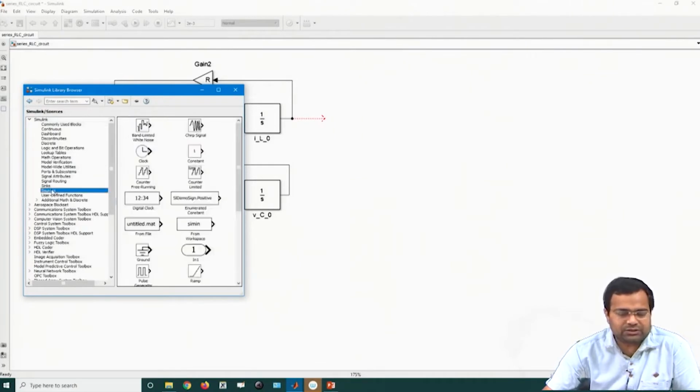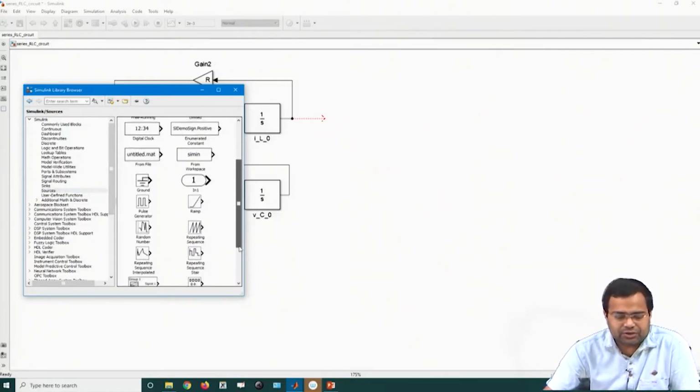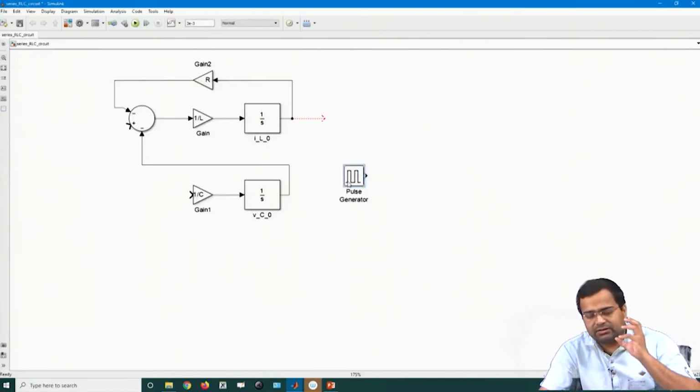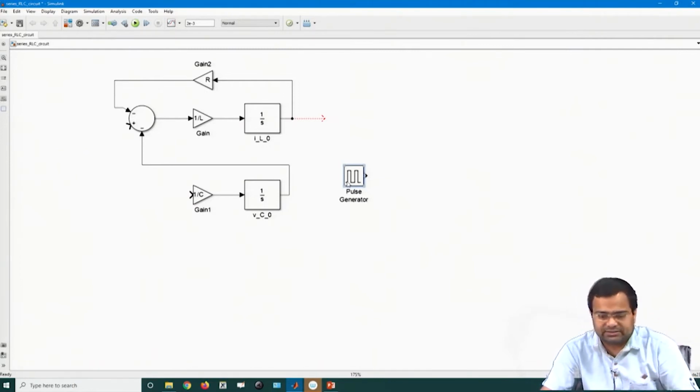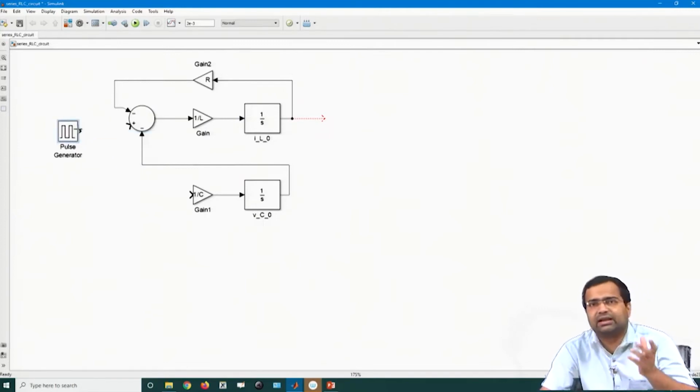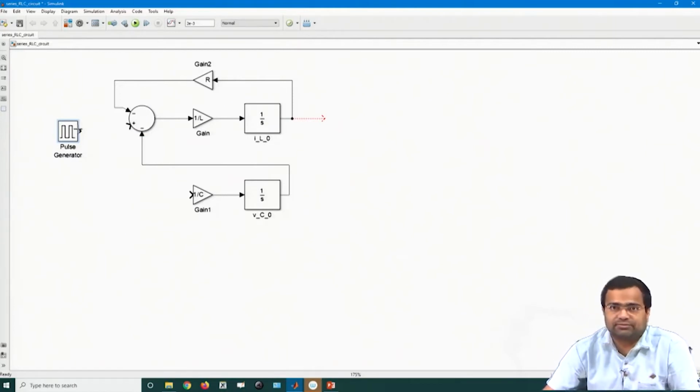If you go to source, in the Simulink library, there are various types of source. So, let us say I choose a pulse generator, that means I want to give a DC for a short time, then 0. So, repeated pulses. You can generate any other signal also, a sine wave AC, DC, even you can put custom blocks for simulation, that is also possible. So, we will slowly move into more complex blocks, but we will start with a simple block.